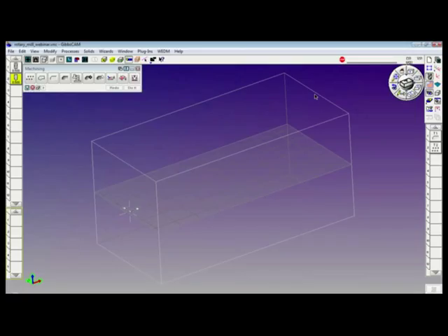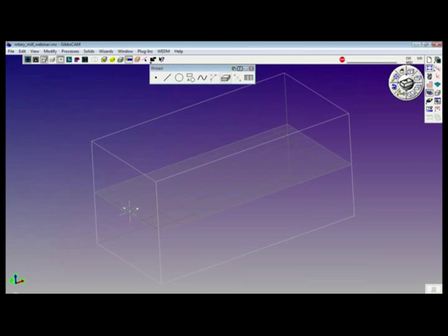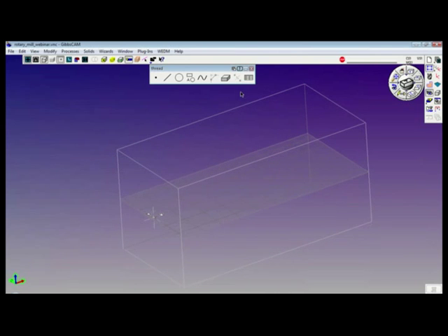First off, we bring up the geometry creation palette. I'm going to turn off the tool list and the cam list for now. A little bit less clutter on screen. As I mentioned, we create 2 points. The first point, X, Y, Z, is created in linear mode: X 0, Y 0, Z 1.5. Multiple feature creation tile creates the first point right at the beginning of the thread.